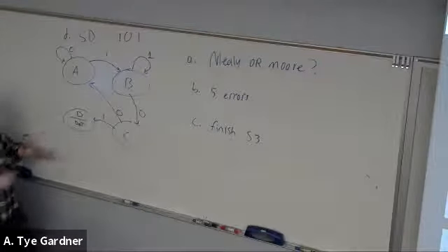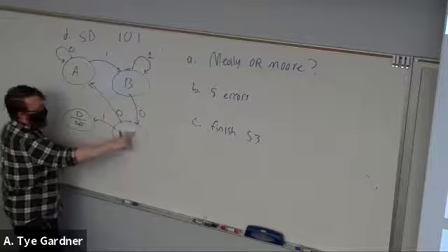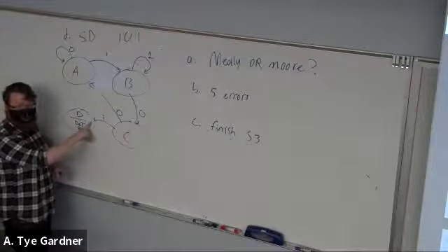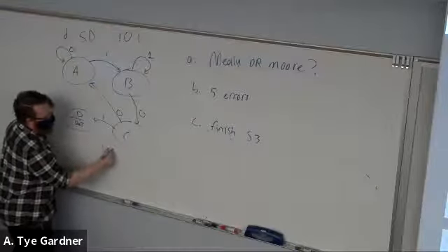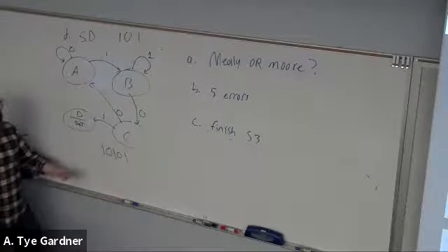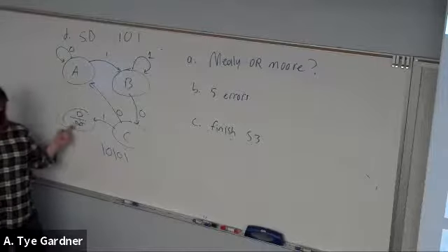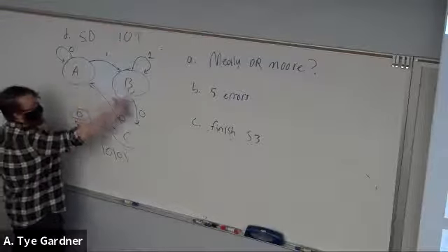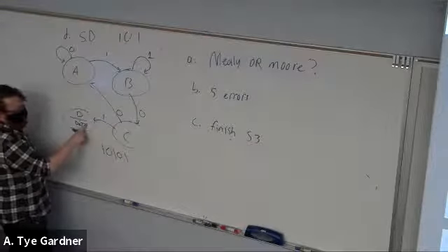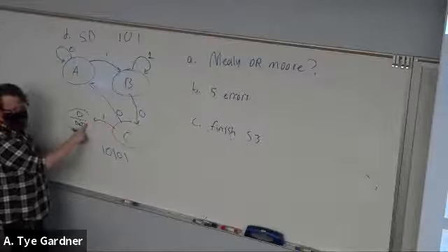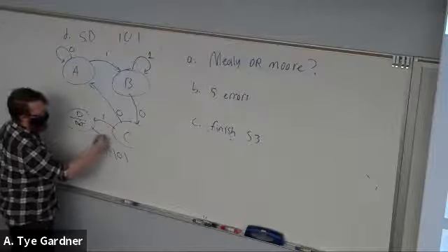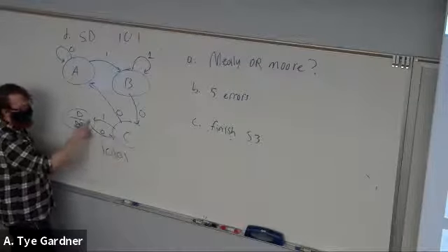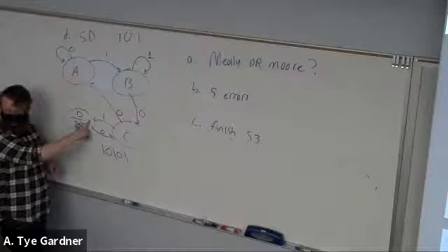Okay, now if I do 1, 0, 1, I've got my detect, and I should detect overlapping sequences of 1, 0, 1. So this is a good idea to make sure that this just says detect twice, right? That was what I said. Make sure this happens. So I go 1, 0, 1, now 0. Go back to C. Exactly, because I need to be in a point, so when I see another 1, I get detected.